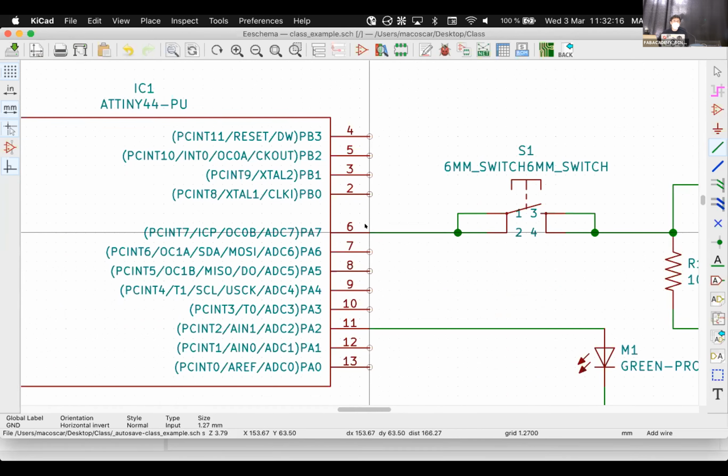It's very sensitive. It's like one of those days when everything affects you, it's the same, you know? When you set this pin as an input and you don't connect anything to it, it could be high or low for many reasons. It could be because someone touches it with a finger, because there's electromagnetic interference around it, because the other pin is high, random things, okay? So we need a way for it to be in a good position when the button is open. So here we already have a problem, okay?